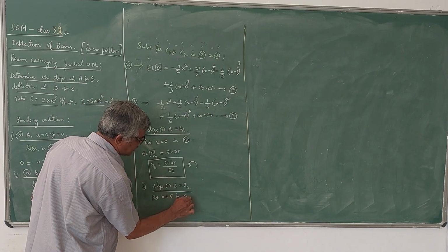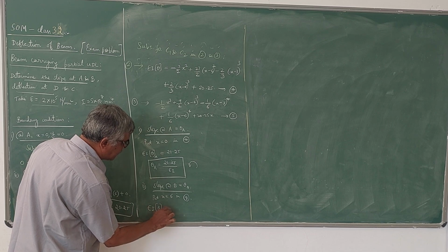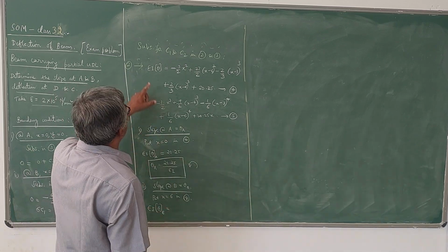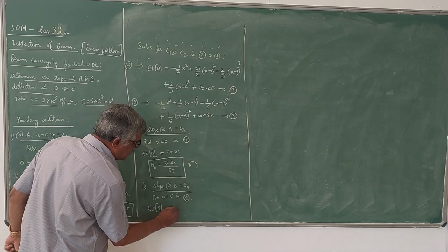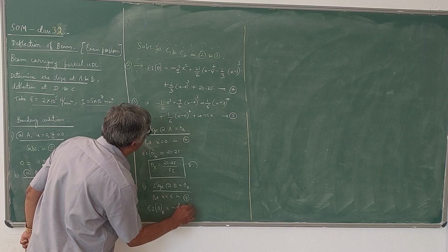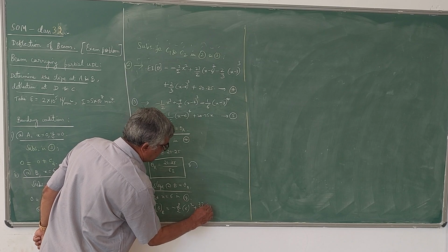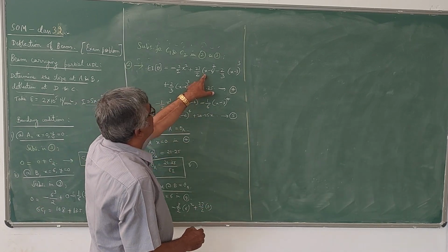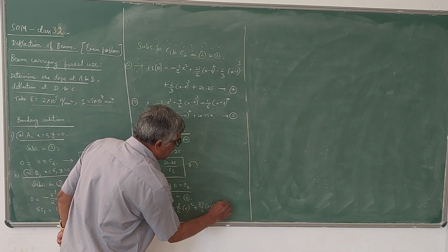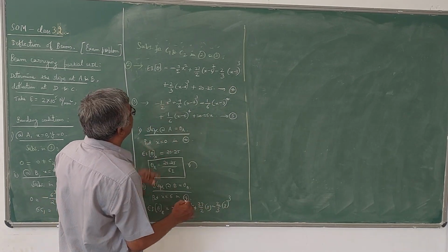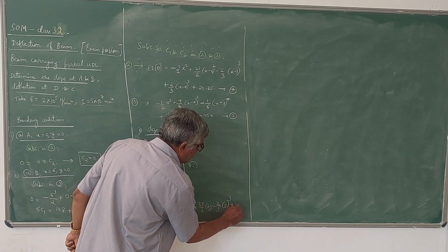So in same equation 4, EI into theta B is equal to, now put x is equal to 6 here in this equation 4, minus 3 by 2 into 6 square, plus 27 by 2 into 0, it becomes 0, 6 minus 6 will be 0, then 6 minus 3 will be 3, so minus 2 by 3 into 3 cube, you will get, then this one 6 minus 6 becomes 0, last term 20.25 will be there.